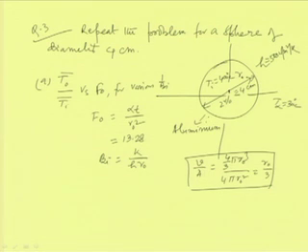So the properties of aluminum apply and these values are the same. We get 1 by Biot equal to k by h R naught, and that value again becomes 21.5.